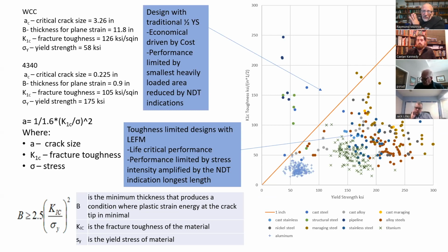But maybe after we talk about heat treatment, I'll try and put together something where we can talk about toughness and Charpy V-notch, because there is at least one new thing in that field called a master curve. And the master curve says that if I know where the nil ductility temperature is, I know what the fracture toughness is for all thicknesses and all temperatures. And so that old work that you were talking about, Paul, we actually put together something to estimate the nil ductility temperature, because that was a big thing for Polini.